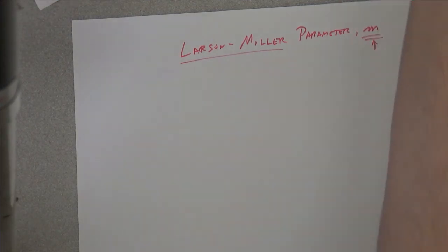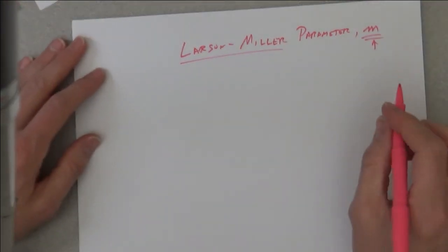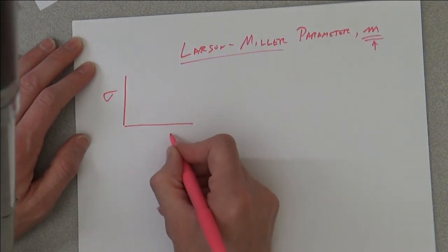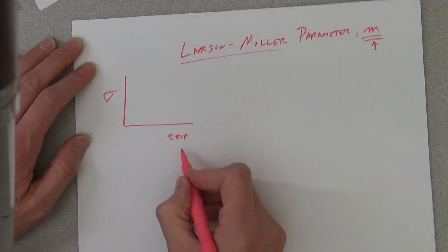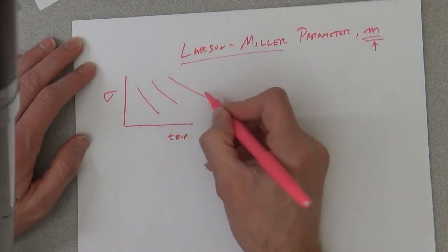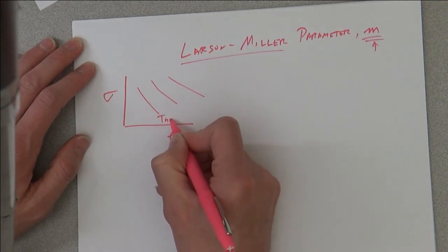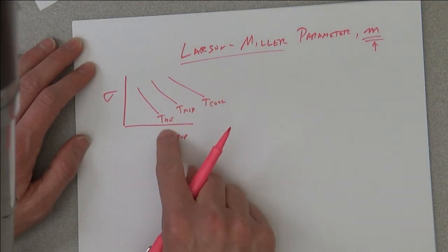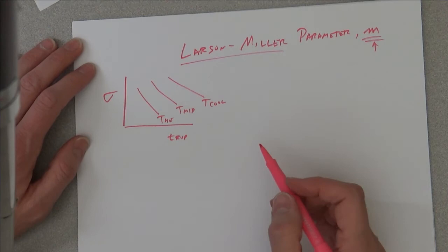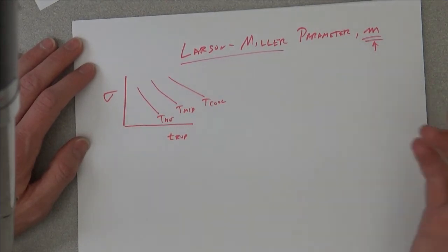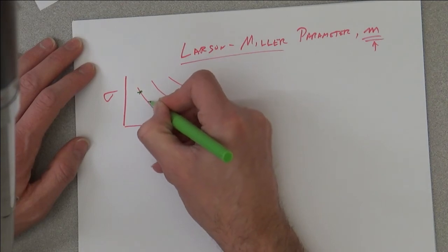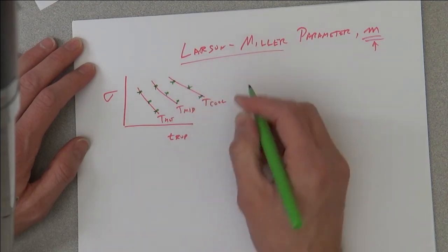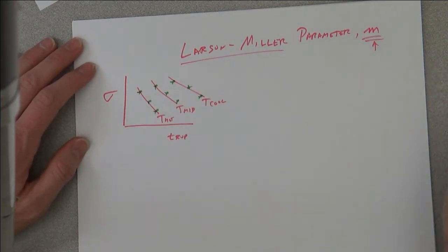So the basic idea is that if you're given a set of, say, stresses versus t rupture for, say, a couple different temperatures, right, because the hot one's going to be shifted to the left here. And for example, you have a company, and the company invested to get a couple data points, and you get these curves.